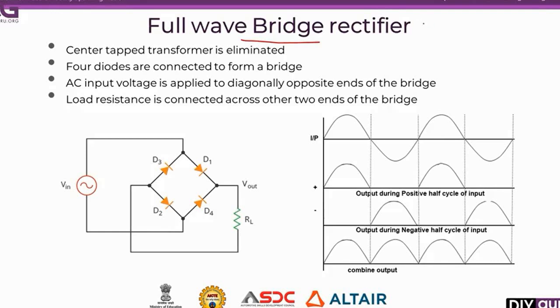See, this is the rectifier circuit which is commonly used for many practical applications. So this is the actual circuit diagram of the bridge type rectifier. If you see here, the center tapped transformer is completely eliminated. Instead of that we will be having additional 2 diodes as you see in the circuit diagram. We have D1, D2, D3 and D4, numbered in such a fashion depending upon the conduction they have. This is the input waveform and the output waveform. Now we will see the actual working of the full wave rectifier.